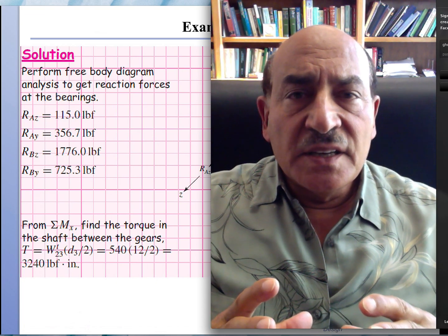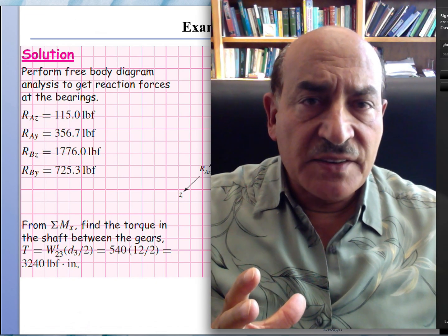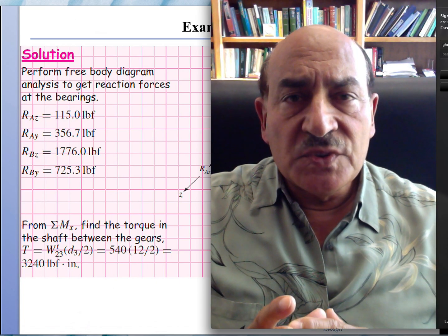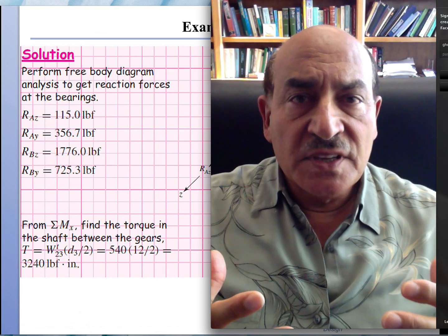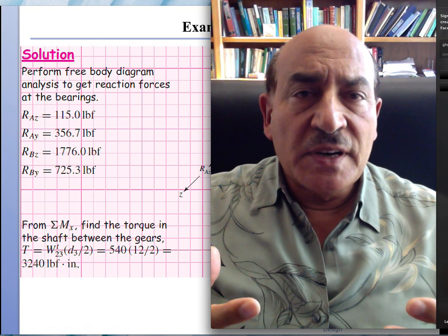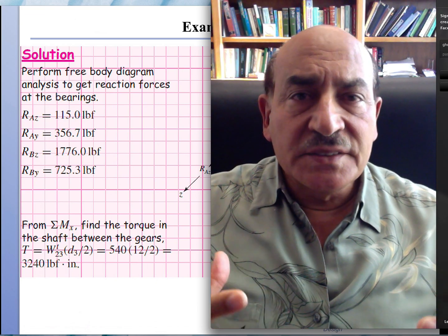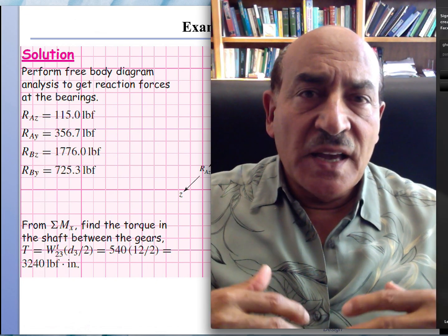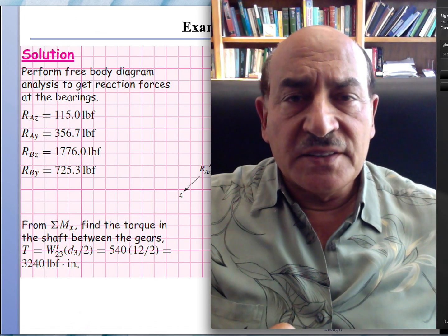Note that at the end of the day, there's going to be a torque distribution on the shaft, and there's going to be a moment distribution on the shaft. Moment is also a vector, so we think of moments as vectors. We'll get two components of that vector, and then we'll add them up vectorially, so we can produce a distribution of the resultant moment vector over the entire shaft. And once we have that, we can proceed with doing stress calculations.